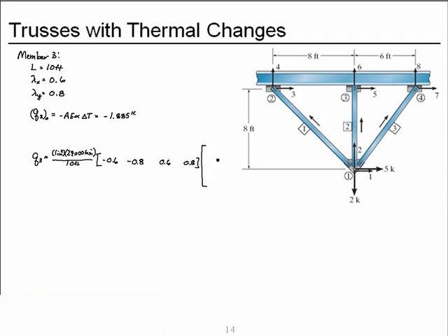The displacements for degrees of freedom 1, 2, 7, and 8. 1 and 2 we saw, and minus 1.035 times 10 to the minus third feet. Then degrees of freedom 7 and 8 are supported or constrained, therefore their displacements are 0, and we add our fixed end force.